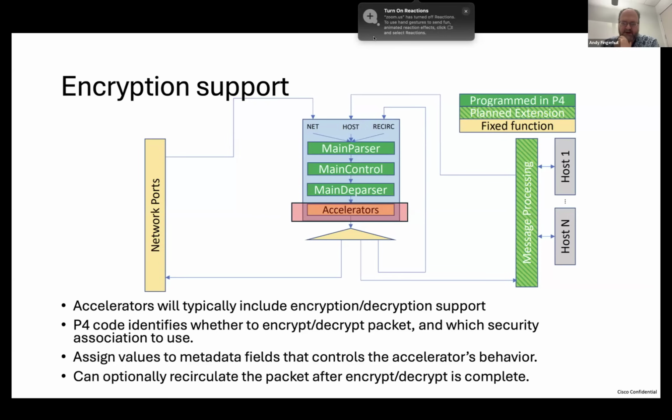So in several smart NICs, there are specialized ASIC gates for payload encryption and decryption. I'm not claiming that's universal, but it's enough work per packet and per byte. The reason why programmable NICs and switch ASICs exist is not because CPUs can't do these things, right? It's because while you could do them with general purpose CPUs, the price, power, and performance ratios are terrible compared to switch ASICs and programmable NICs.